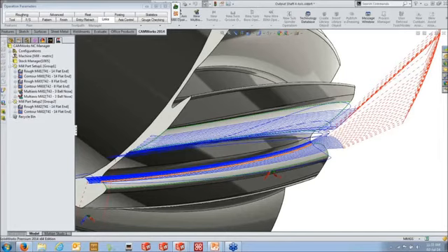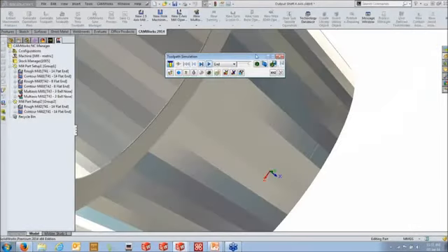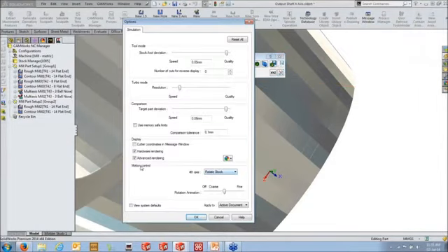How do we control in the simulation if the tool tilts or the part rotates? Good question. So in the simulation options, if you wanted to simulate this right now, this is where we go and define it. In the motion control fourth axis, where it says to rotate stock or rotate tool, these settings are only going to be appropriate for the indexing or the positioning side of it. If I switched it out here to rotate tool or rotate stock in the multi-axis operation, it's not going to actually change it. So these are only applicable to the 2.5 axis index positioned stuff.